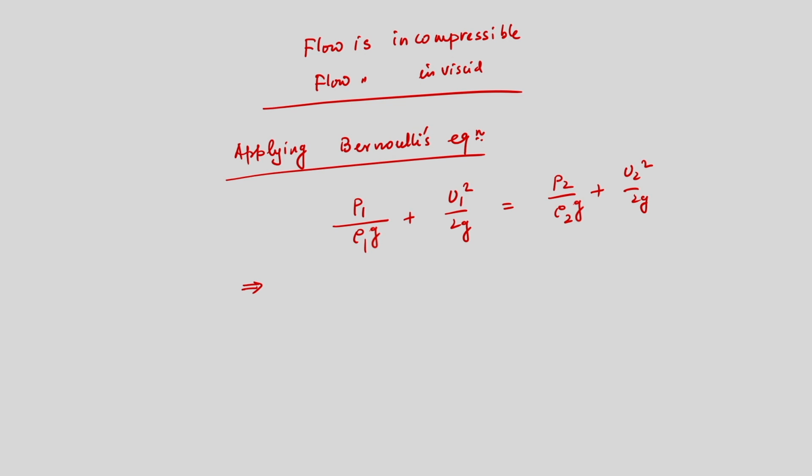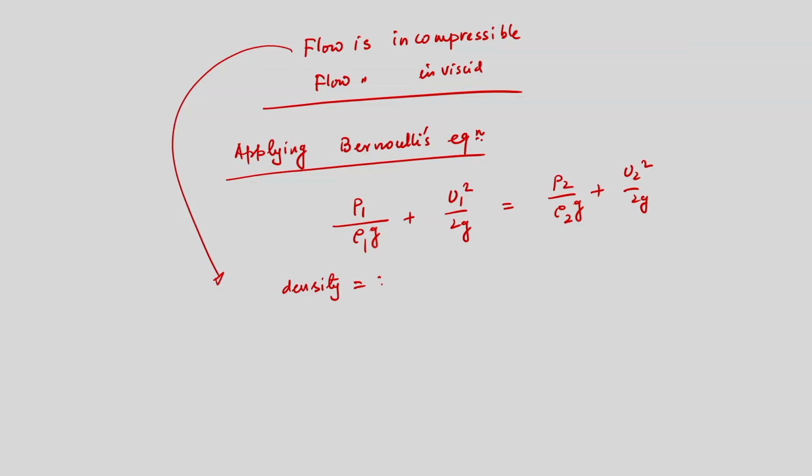And from there, in fact, I am not going to write that. As we consider incompressible flow, I am considering density is also constant. Constant density is a special class of incompressible flow, but fine, for the time we are considering the flow is incompressible. That does not mean that density will be constant. Density may change in space and time in such a way that the total substantial derivative will be 0, but we are going to consider that the density is equal to constant.